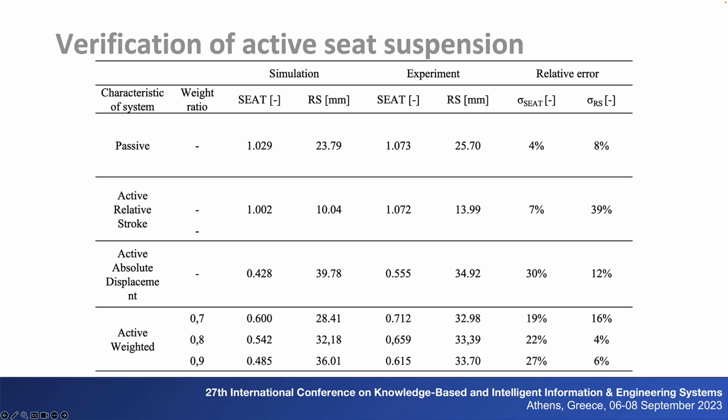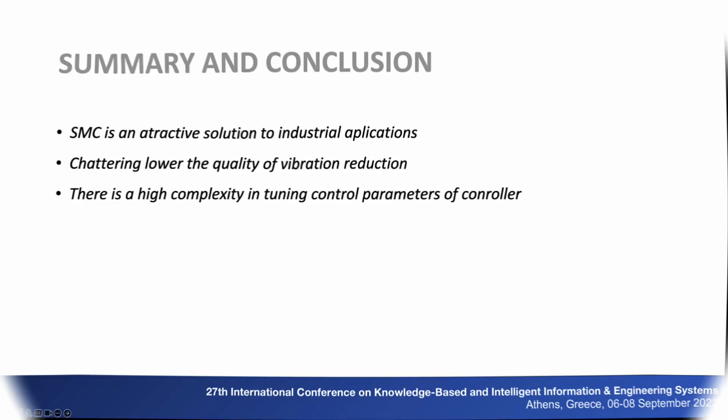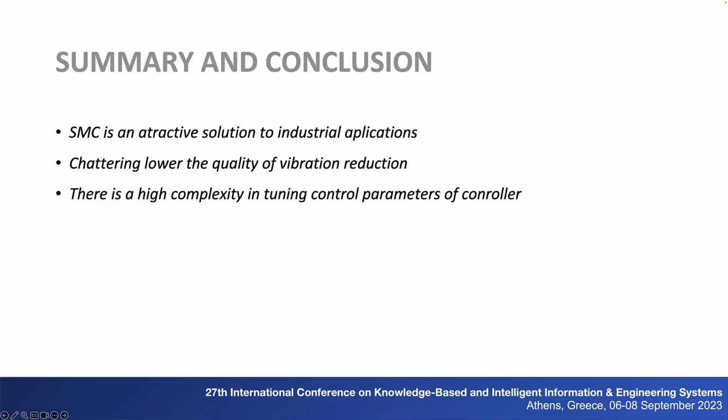An application of the weighted active force in terms of minimizing the conflicting system requirements allows to increase the effectiveness in vibration isolation of the suspended body while maintaining the relative stroke of a suspension system at an acceptable level. This presentation shows a mathematical model of an active horizontal seat suspension system with the sliding mode controller, as well as its verification through simulation and experimental research.